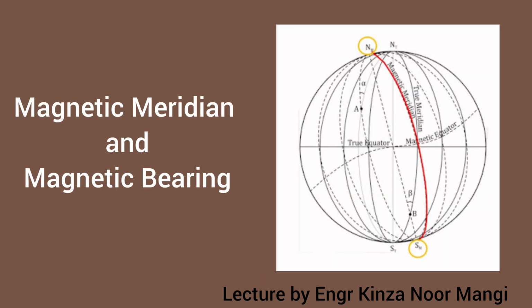Okay, so next is the magnetic meridian. When a magnetic needle is suspended freely and after some time it is balanced properly, unaffected by magnetic substances, it indicates a direction. This direction is known as the magnetic meridian. The angle between the magnetic meridian and a given line is known as the magnetic bearing, or simply the bearing of the line. And again, the angle is a horizontal angle.